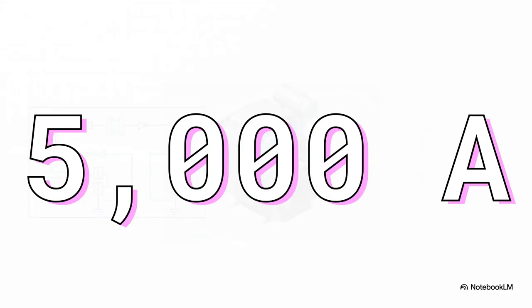And here we go, the moment of truth. We just use good old Ohm's law. Current is voltage divided by impedance, and we calculate our short circuit current. And look at that number, 5,000 amps. Wow. To put that in perspective, that is almost 20 times our normal operating current.